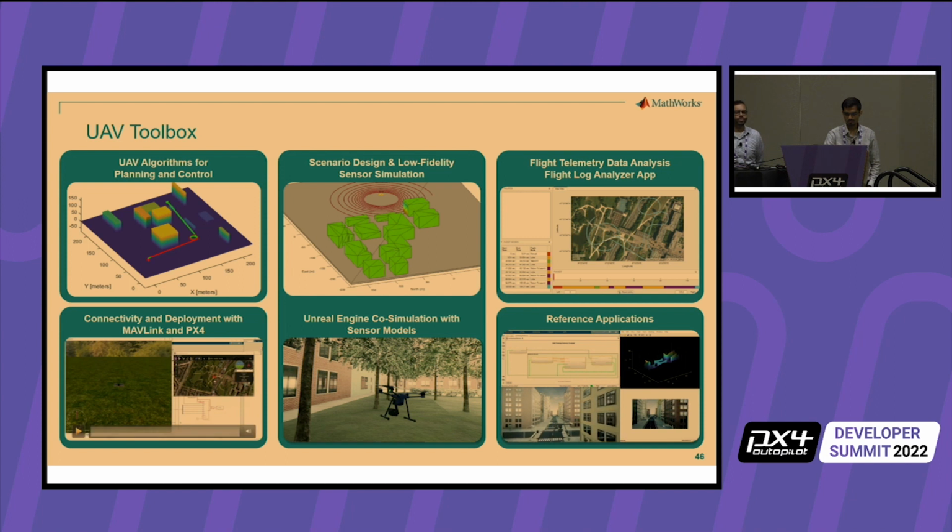I don't know if Unreal Engine has any kind of wave propagation in it. We actually have other tools, Mapping Toolbox and RF Toolbox, that will do that for you. We can take the position of the drone from Unreal Engine, and you can state where your antennas are and see what kind of coverage you're getting. You can do that in Simulink. You don't need it as part of the visualization, but it can be another model that does that for you. Thanks for the questions.